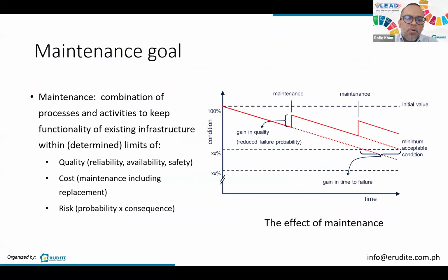And so when it runs for a certain period of time, more and more dust is collected over the panel, and let's say they do a cleaning, a maintenance is done, you have an improvement in performance, a small but worthy improvement. If you do not do the maintenance work, it continues to degrade. You also have more heat generated because the performance is less. So your degradation starts to go on and on. And if you don't do maintenance, you have a remaining life of, let's say, here.